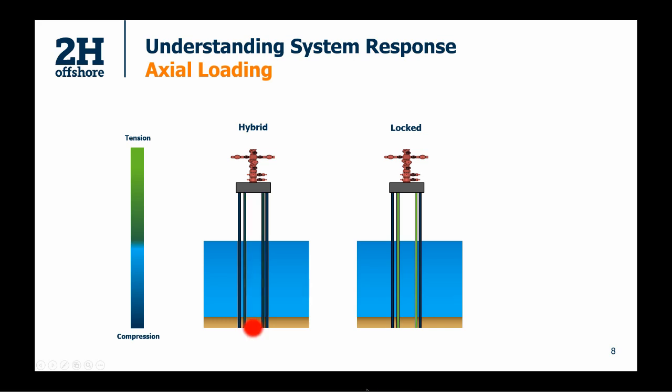As we move into production, we start to see the thermal effects from downhole, and what that means is that the surface casing is going to want to expand as it heats up. And in doing so, it wants to push up on the wellhead, but it can't move because of the wellhead and it can't move because of the hole, so it starts to go into compression. And it will do that until the point that it has sufficient compressive load that it can overcome the weight of the surface equipment and the internal casings. And what you'll find then is that that's when you start to see the wellhead move. The point is that once that's occurred, the conductor is no longer in the high level of compression that it was. It's now just sitting under its self-weight. But your casing string, which was under tension, is now in a reasonable level of compression because it's now the supporting mechanism for your well.